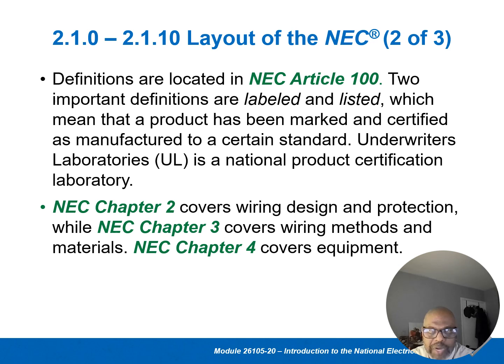If you're looking at wiring coverings, like the insulation on the wires, and whether it's permissible, for example, if you're going to bury wire underground, what needs to be around that wire to protect it? Because there may be chemicals and moisture in the ground, and not all insulation is the same. It may be in areas that are extremely warm, which can cause the insulation to melt or not withstand the heat. So for the insulation on the wires, they will specify what type of insulation based on the type of installation.